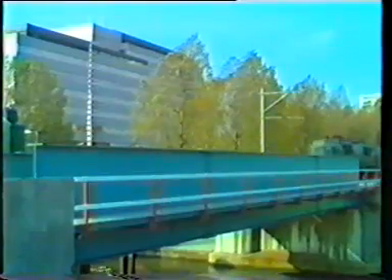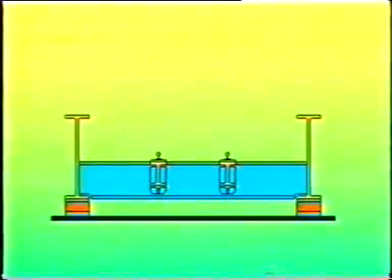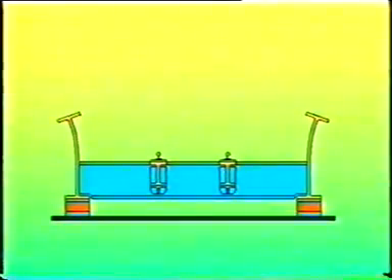The bending moment in the main girder caused by vertical loading introduces compression in the upper flange and might lead to buckling. The end portals, composed of end cross girders, brackets, and the main girder, are usually constructed with extra stiffness so as to fix the upper flange. Without intermediate U-frame stiffeners, the buckling length would be equal to the span of the bridge, resulting in very low ultimate stresses.